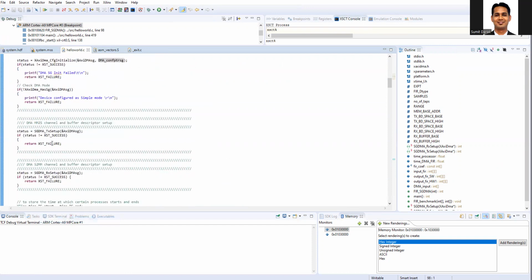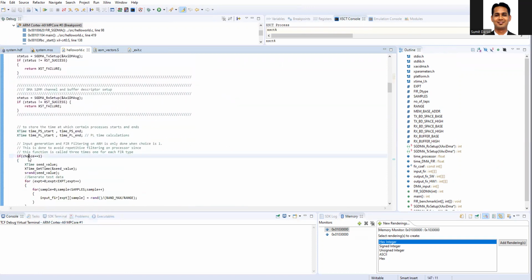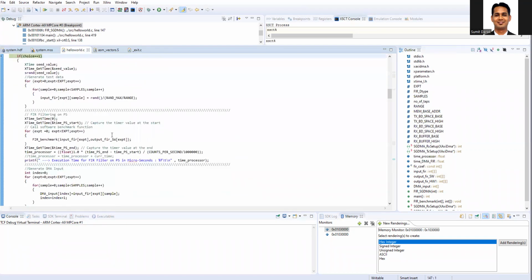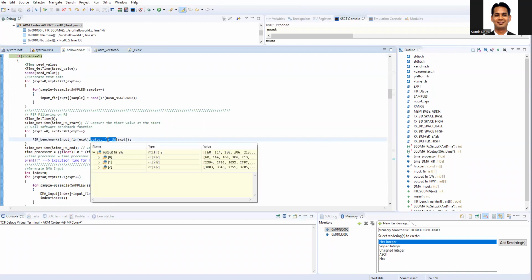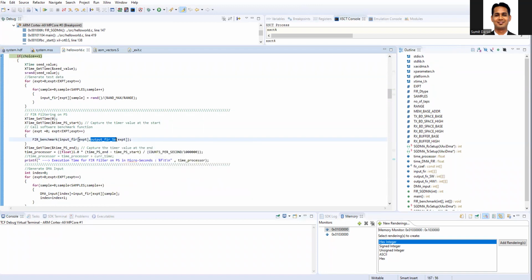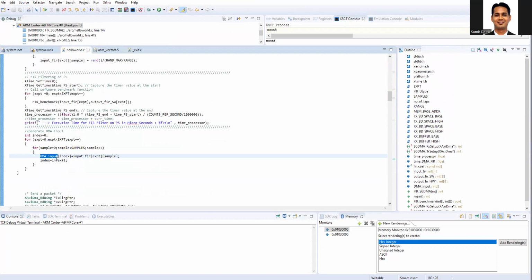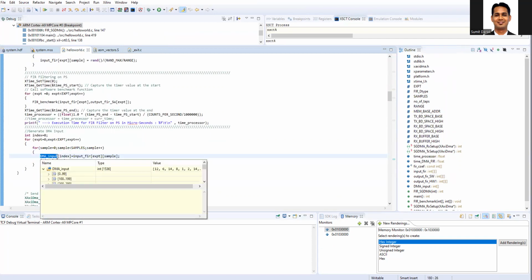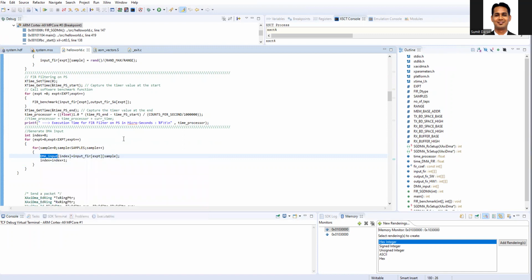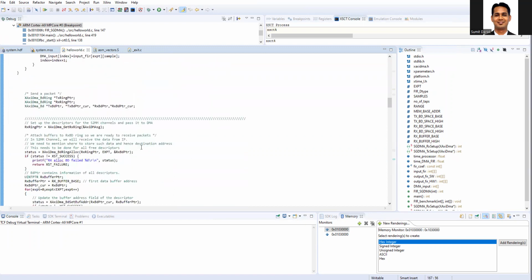Now that the DMA gets configured, the implementation on the processor is not needed because I have already created the reference output, which is a global variable. The corresponding input I have also already created. This is the global input, so I don't need to regenerate it for every filter. This DMA will take the DMA input, pass it to the HLS IP, get the DMA output, and this will be compared with the same benchmark output which was generated in the first call.